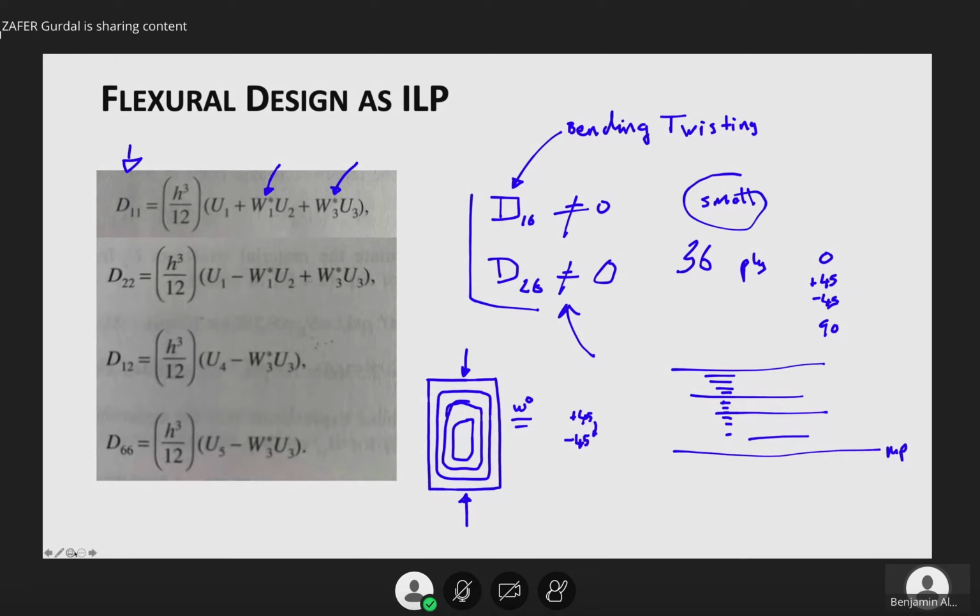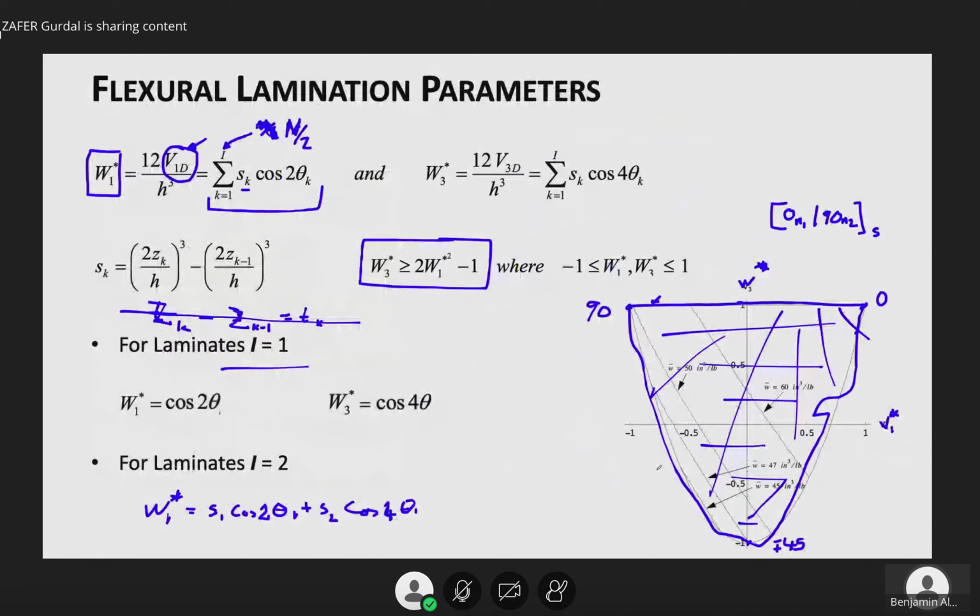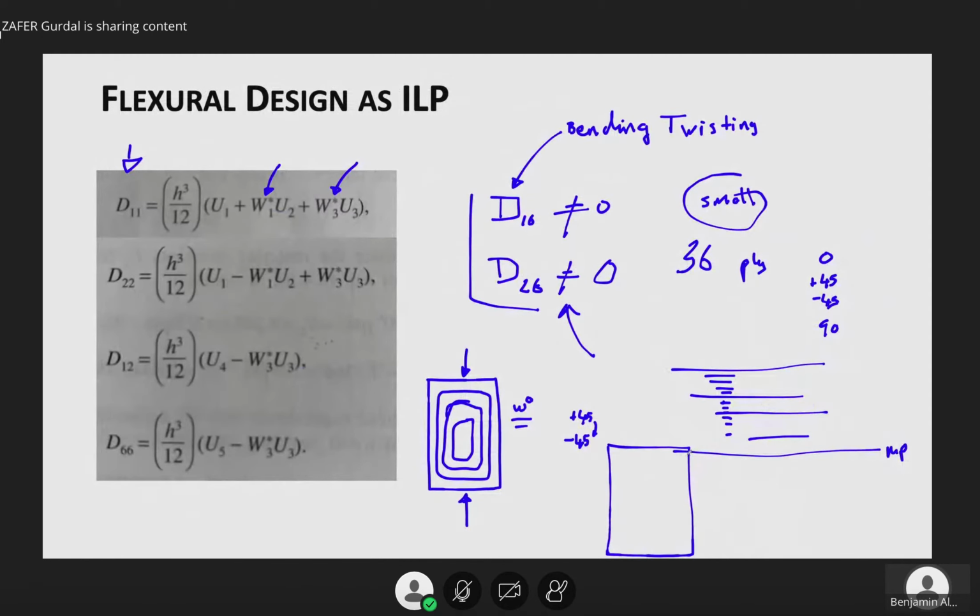If, on the other hand, there is large coupling between the bending and the in-plane stiffness terms, as soon as this plate starts experiencing out-of-plane deformation, then depending on the sign of the buckling, the out-of-plane deformations are going to have a bias towards one direction.